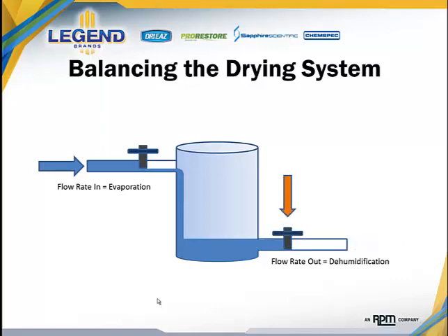And let's say, for the sake of argument, that water is evaporating into the air at a faster rate than dehumidification is removing it from that same air. The consequence is that humidity will increase over time. The challenge with making this assessment, however, is that in many cases the wrong measure of humidity is evaluated.